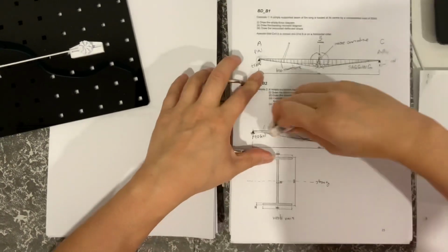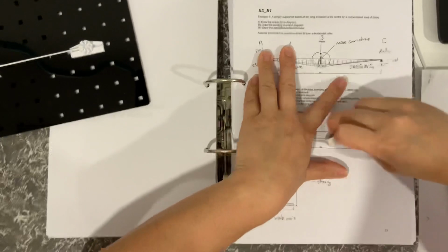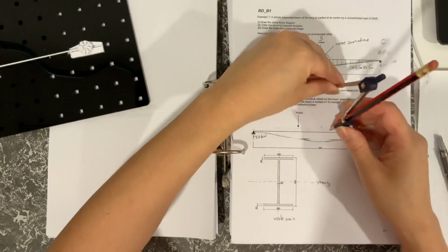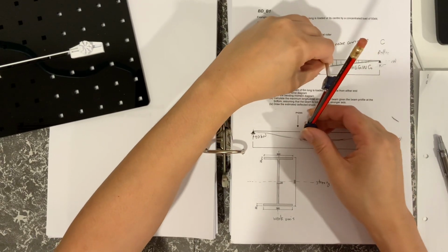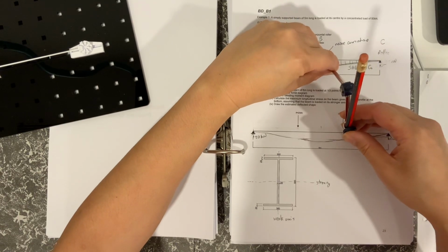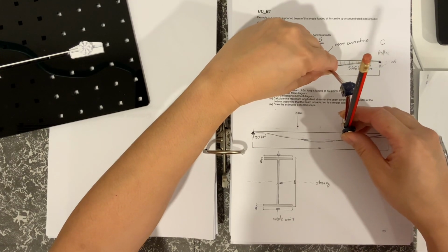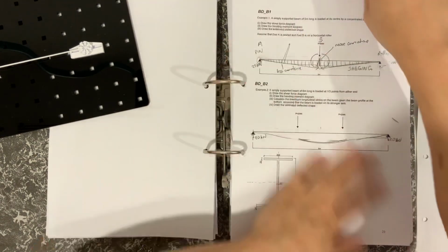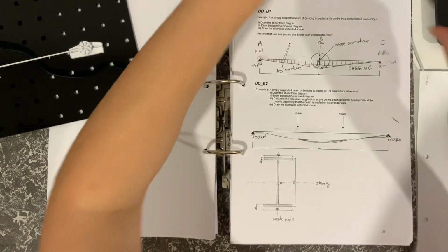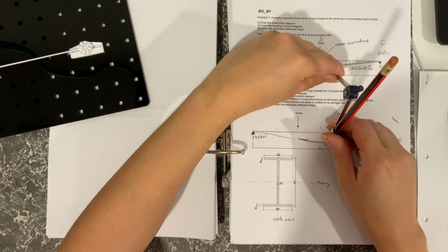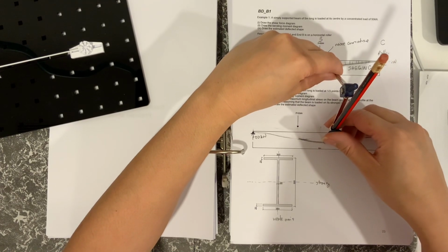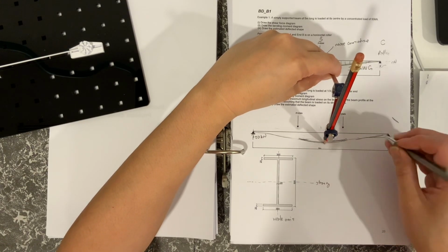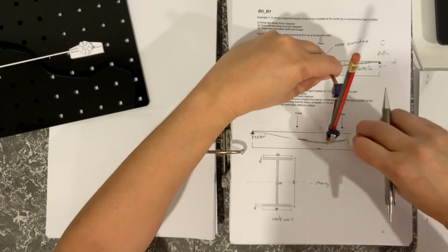So I'll get rid of the bending moment and shear force diagrams, and I'll try and show that there. Okay, so let's get rid of that. So what we're basically saying is that because the bending moment there would be constant along that portion, that would have a radius of curvature that would be constant around there. Okay, so the radius of curvature, if it's going to be drawn like that, it would look like that.